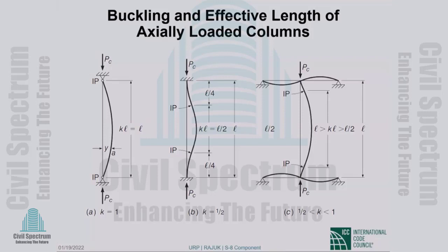That's the language that is used. Braced against side sway, what we were discussing on the previous page. Okay. If it is a braced column, typically the ends will be neither fixed nor free. The column will frame into a beam or a slab at both ends, and the beam into which the column frames will provide some restraint that will be between this and that.